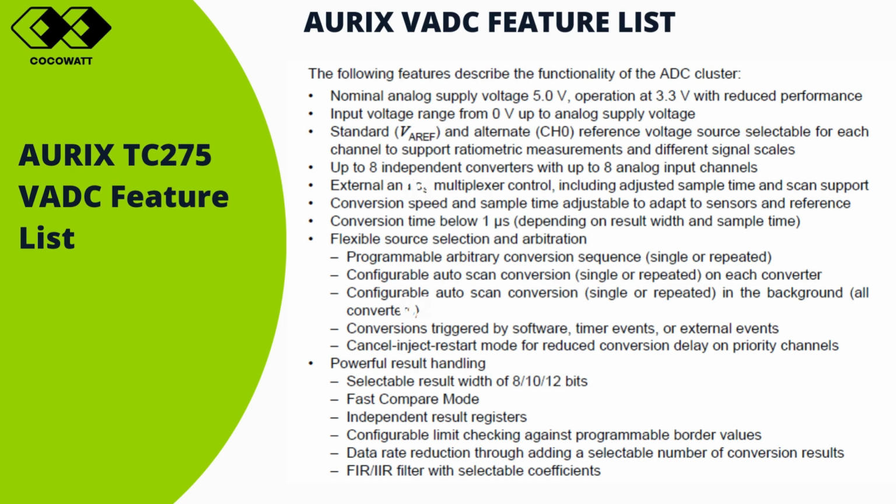The ADC cluster offers flexible triggering and sequence options. You can program the cluster conversion sequence, set up auto scan operation either per converter or across all converters, and trigger conversion manually, through a timer, or via external events. It even supports cancel-inject-restart modes, which help prioritize urgent channels and reduce conversion delay.